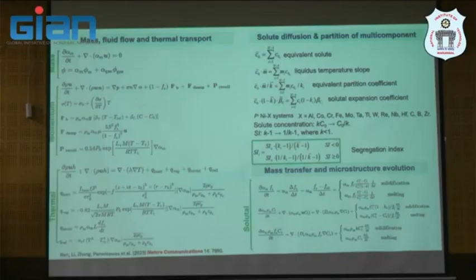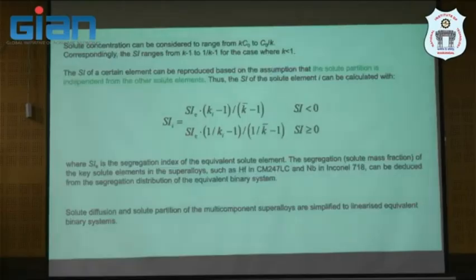So that means for the different nickel-based superalloys, you do a pairwise calculation for each system coupled with available thermodynamic data, so that you can extract the solute concentration and these partition coefficients, K, which I will talk about a little more later, linked with process conditions like the Péclet number. And then you use this to develop an understanding of how the microstructure evolved.